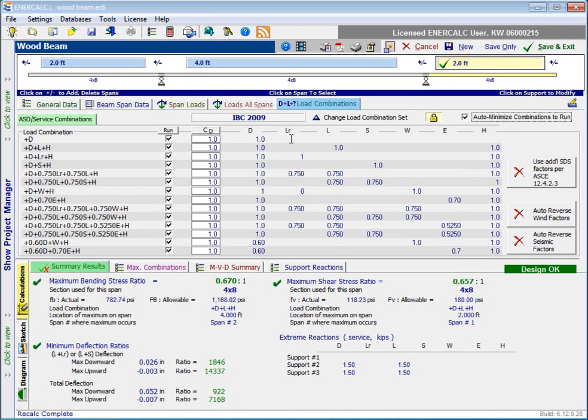and these are all of the factors associated with the combos. The next thing that I'd like to point out is that load combinations are something that need to be looked at closely. And when you read the codes and the design standards, there are some factors on some of the constituent load cases that need to be modified on occasion. What we provide is a basic set of load combinations. We expect that the user will probably have reason to want to go in there and modify certain things at certain times. For instance, maybe it's the factor on the earth pressure that needs to be adjusted based on the nature of the earth pressure load in the particular analysis that's being done.